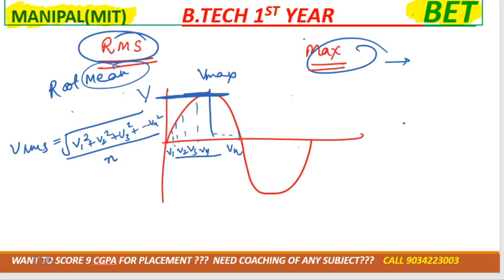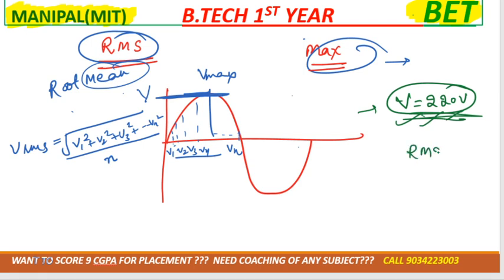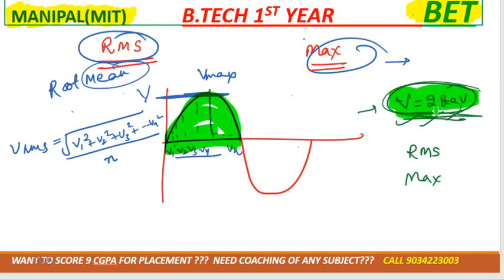Now I am saying at your home you are getting a voltage of 220 volt. Now tell me, according to you, is this 220 volt the RMS voltage or the maximum voltage? Can you tell me? Because RMS includes all the voltage, RMS has covered the complete waveform. So 220 volt is the RMS voltage. That's why I'm saying that in every calculation we have to use RMS voltage.